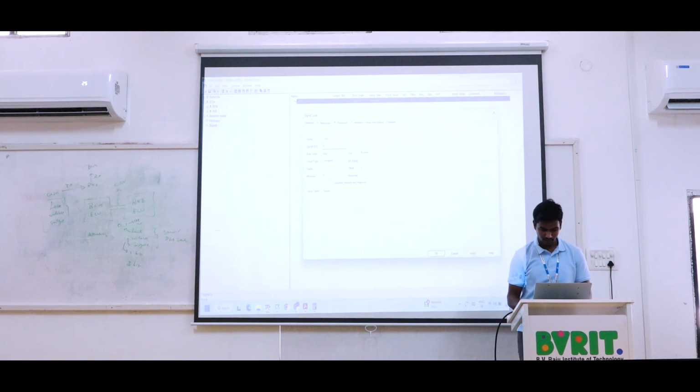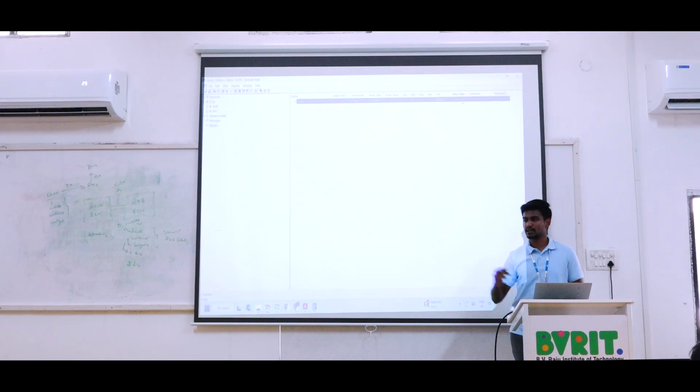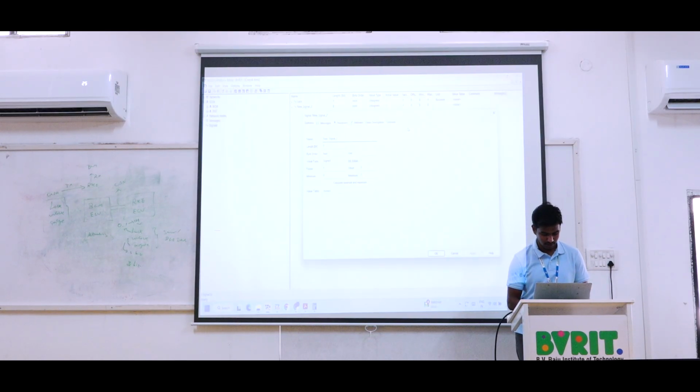Okay, so now we can take the 1 and the values will be changed. The value type is constant, initial value is 0, factor and offset, minimum 0, maximum 1, unit type. Since we mentioned the value table, we will get the value table also. The comment we need can be added. This signal is created for the RKE purpose. In the same way, we have created another one.